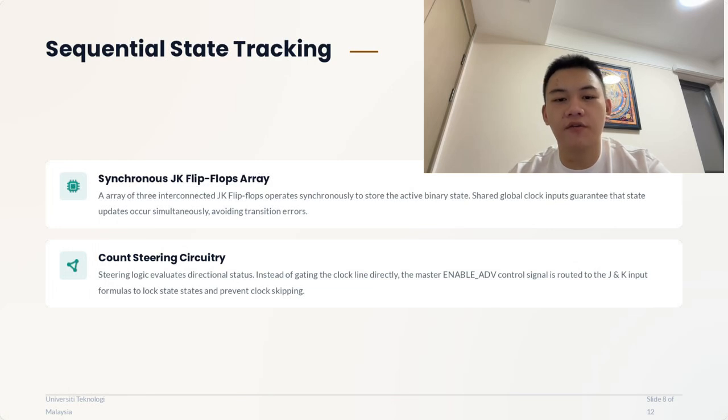We also use two 4-bit adders. The internal counter uses values from 0 to 7, but the actual floors are numbered from 1 to 8. Therefore, each adder adds binary 0001 to the internal value.